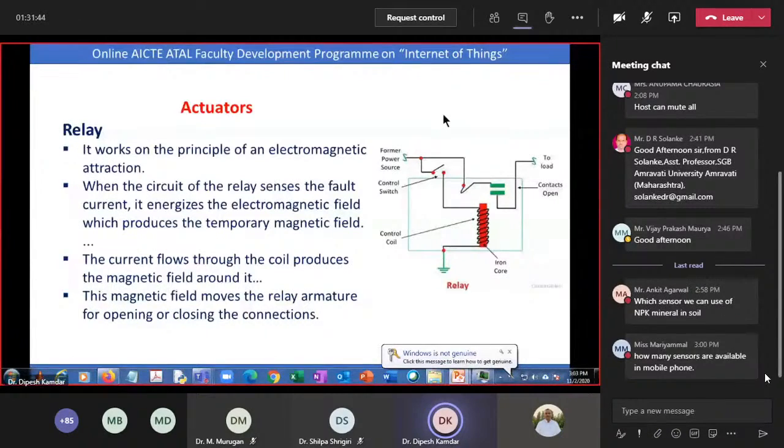So when we need to connect this AC and DC supply, we will have a relay in between. A relay is just a kind of replacement for switches. We can eliminate the switch which we manually turn on or off. It can now be activated or deactivated with the help of control signals.